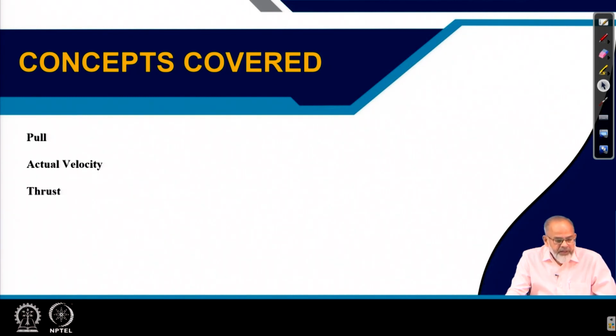But for our purpose, I will keep the load, soil condition and inflation pressure the same, and I will only vary the pull, so that we measure the corresponding slip. Then, knowing the pull values, actual velocity, slip value, the torque you have supplied, and the rolling radius of the wheel, we can utilize those values to find out tractive efficiency.